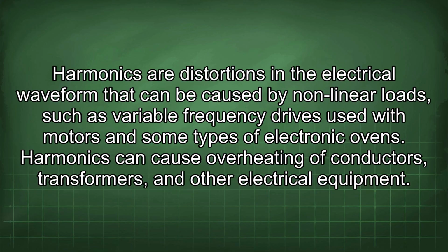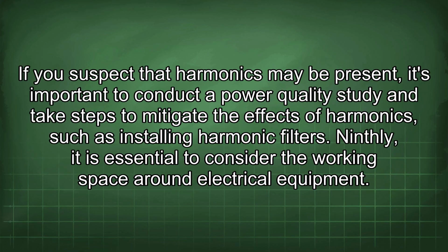Eighthly, remember to consider the effects of harmonics. Harmonics are distortions in the electrical waveform that can be caused by nonlinear loads, such as variable frequency drives used with motors and some types of electronic ovens. Harmonics can cause overheating of conductors, transformers, and other electrical equipment. If you suspect that harmonics may be present, it's important to conduct a power quality study and take steps to mitigate the effects of harmonics, such as installing harmonic filters.